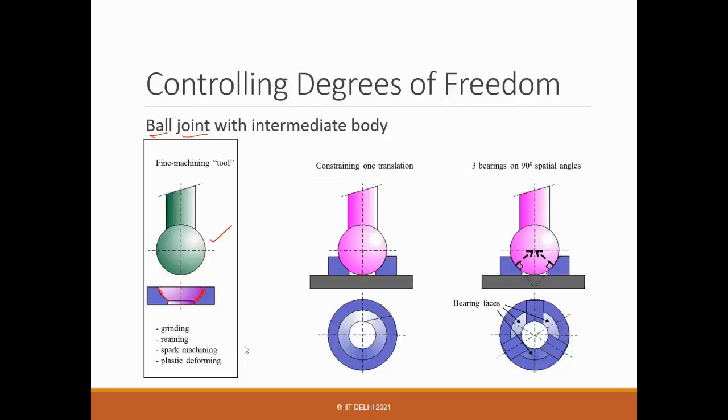So one is the complete surface. So you want to grip from the entire surface, right? Of course, many times at the bottom you want a hole because if the air is trapped, then maybe it will not receive it properly. Sometimes you may have to find a way to provide a nesting force from the top, so you may cover it with another sleeve. Sometimes what you do is create only a partial surface, right?